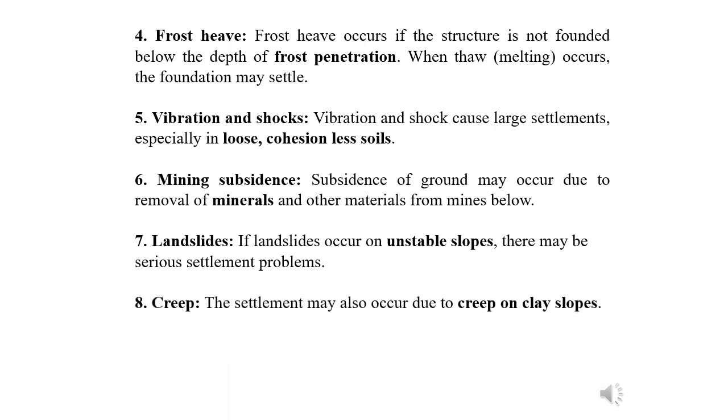Creep can also cause settlement. It is a long phenomenon, right? It comes under the secondary consolidation, secondary settlements. It takes lots of time. It's a time-dependent phenomenon. This can also cause the settlements.